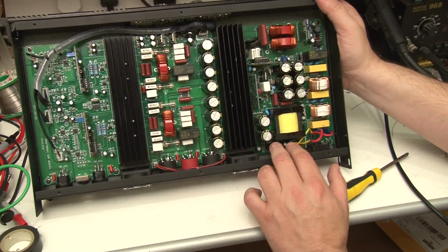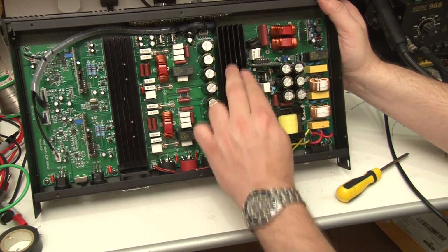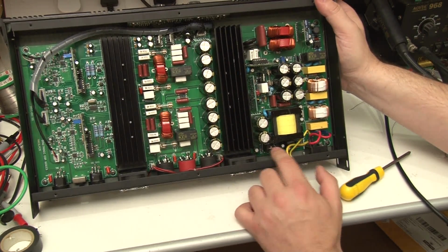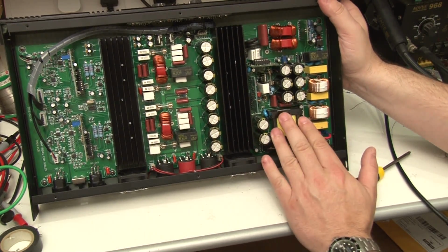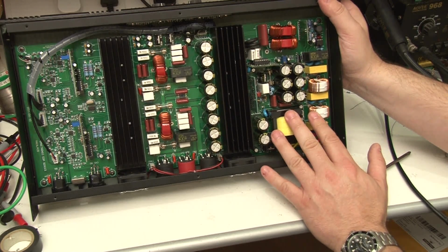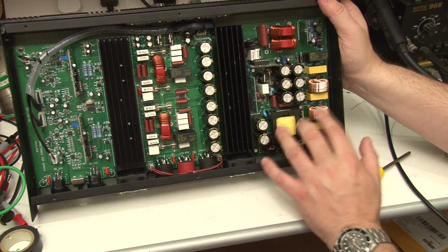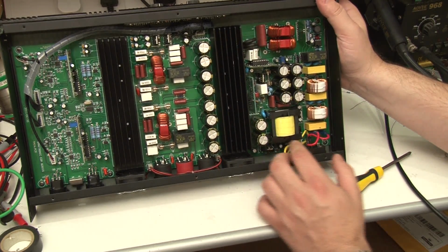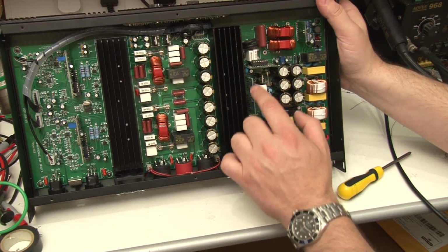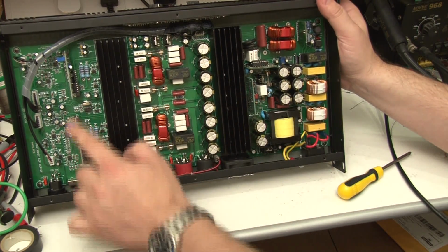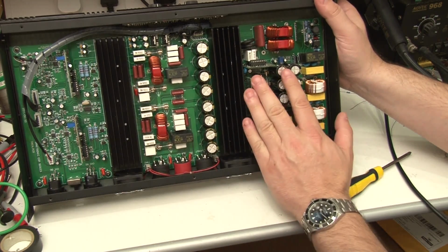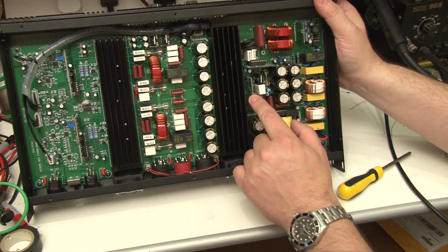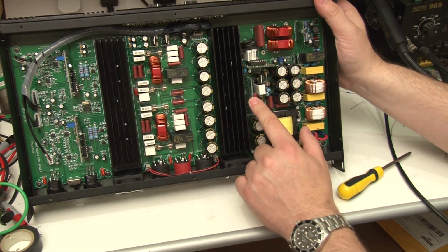The switching devices and the rectifiers are almost certainly under here. It doesn't look like there's any. That could be the switch, I'm not sure, but basically that's a very traditional main switching transformer. Very traditional main switch mode power supply. Nothing sophisticated about it at all. You'll notice the use of a lot of little riser boards in these, and for the most part, that's simply because in these kinds of designs, it's more efficient from a space point of view to put these components on riser boards.